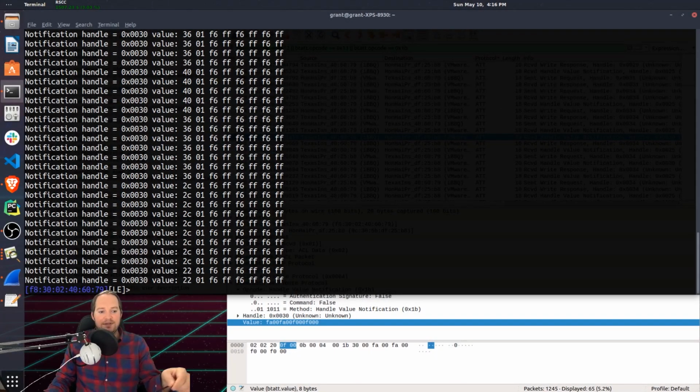If we wanted to see how this works, I can start to touch the probe here, and as you can see, the values start to change on the temperature probe, but we also see that there are values changing in there. So we can see that potentially those first 4 hex digits may correspond to the temperature here.